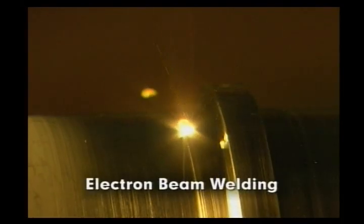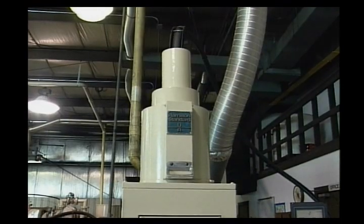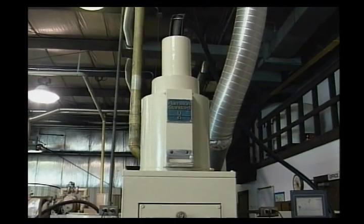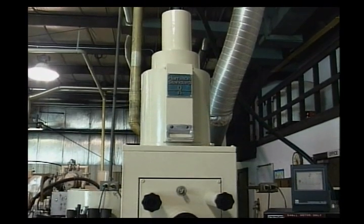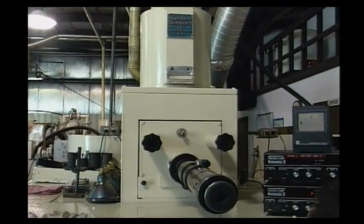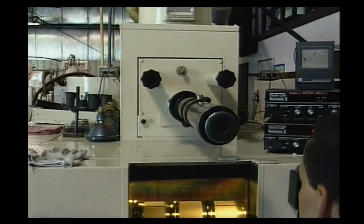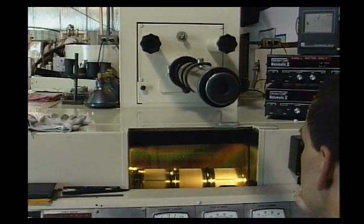In electron beam welding, the coalescence heat is generated by the kinetic energy of a focused stream of electrons directed upon the joint. The electrons are produced by an electron gun, accelerated to high velocity, shaped into a beam by electrical fields, and then further collimated or made parallel and focused by an electromagnetic lens.